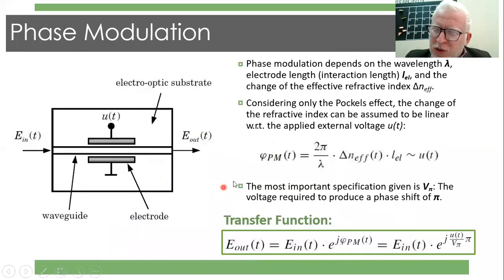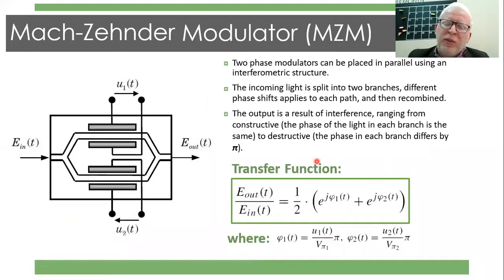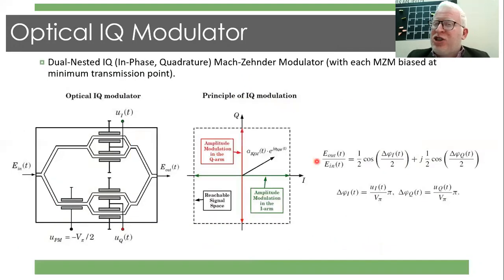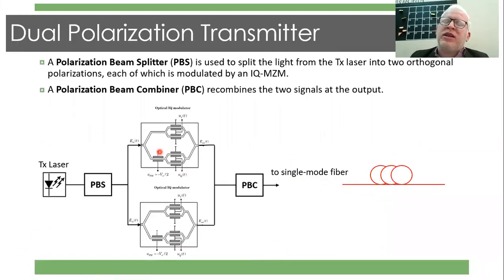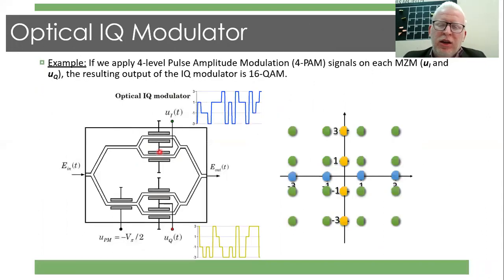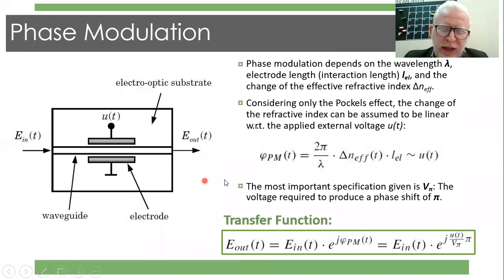because if you remember, my dear student, your phase is inversely proportional to lambda. So you did your calculation for a certain lambda, but the real system is operating at a different lambda. So this is a problem. Another problem, which we are also going to discuss in the next chapter, is called the wavelength line width of the laser. Because usually you are considering the laser as a 100% coherent light source. That's why in this equation, I told you that lambda is constant, because the laser is coherent. It's operating at a certain wavelength. It's a single coherent structure.